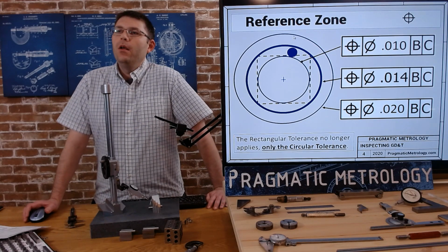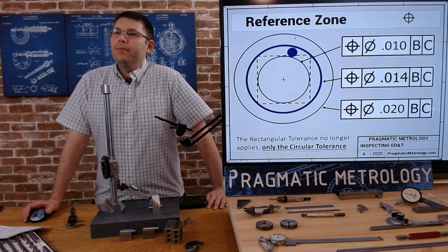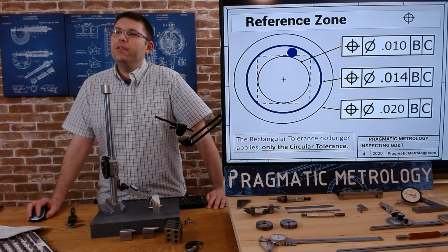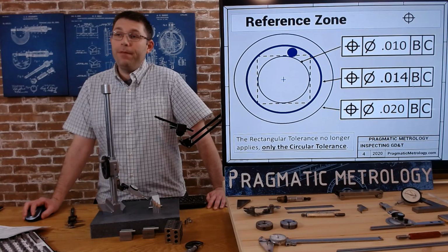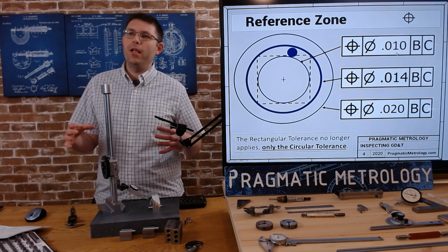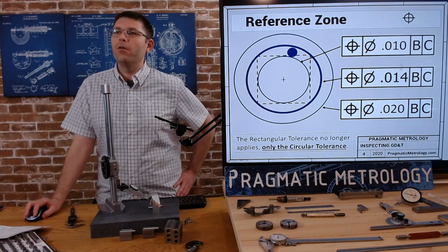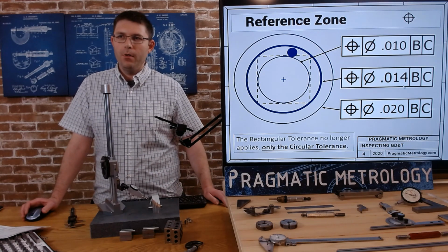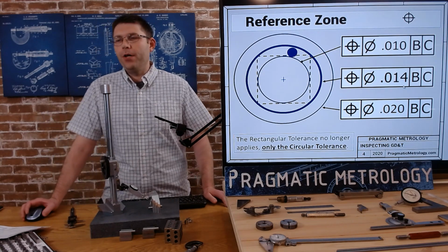So just remember that the difference in these circle sizes has nothing to do with maximum material condition being added. If it did get added, then you could potentially grow your tolerance even more. All 3 of these could grow even more depending on your hole diameter. I don't think I was totally clear on that in the first video.